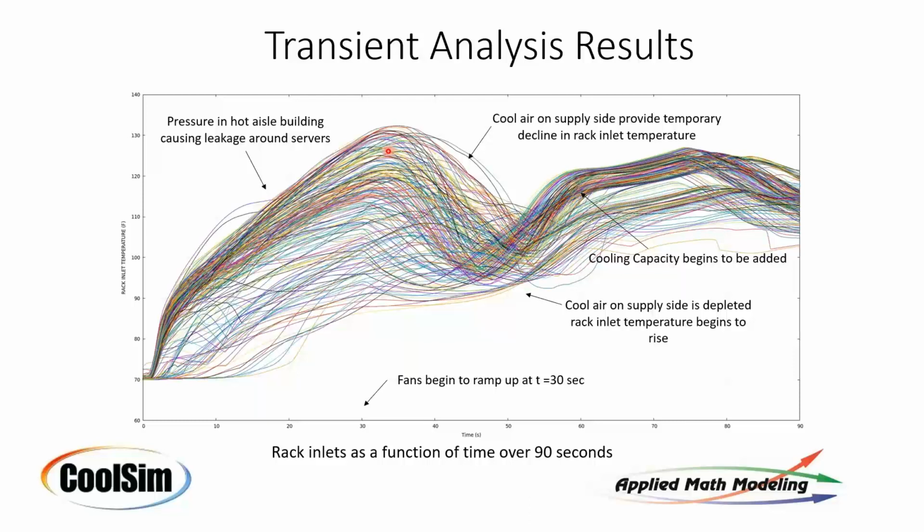Furthermore, if the pressure gets high enough, the IT servers will start to walk a fan curve where they can just no longer push any air at all, and then you have a very, very rapid increase of temperature on the circuitry itself. And then fans kick in, you get a flush of cold air again, coming from the latent temperature that's in the cooling system from the air handler to the rack inlet. And then that bottoms out pretty quickly. You notice that's bottoming out in really just 15 seconds. Because for one thing, you're running at high supply air temps, so there's not a lot of room for margin there. You're already running at 70 degree supply air temp.